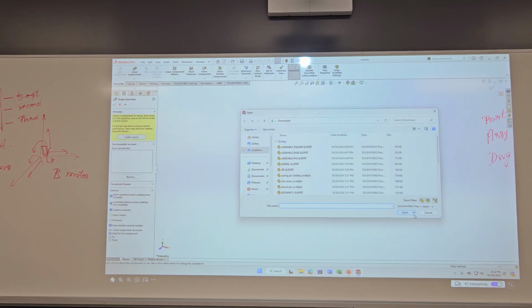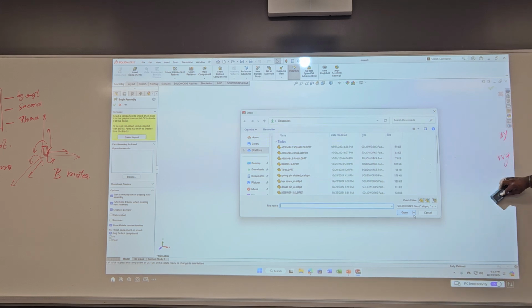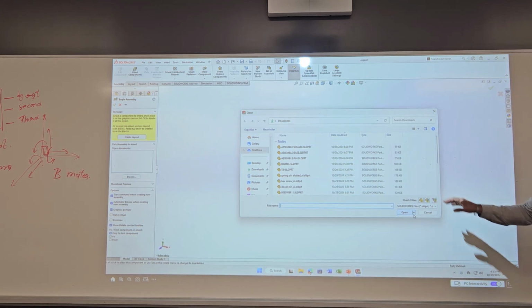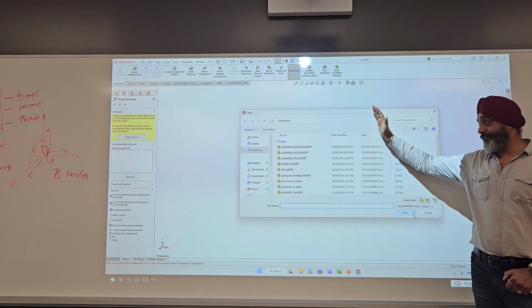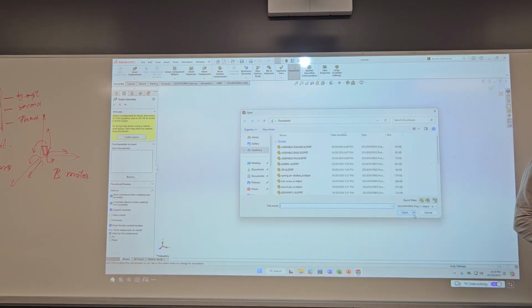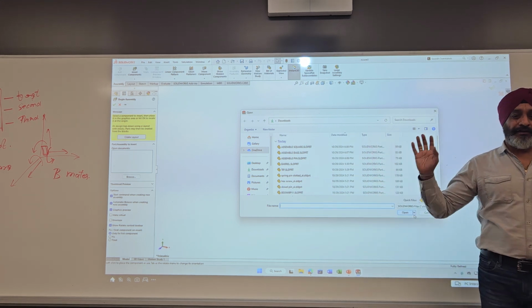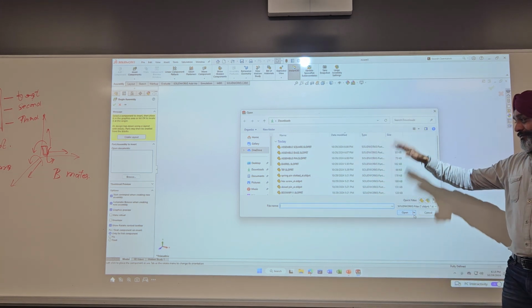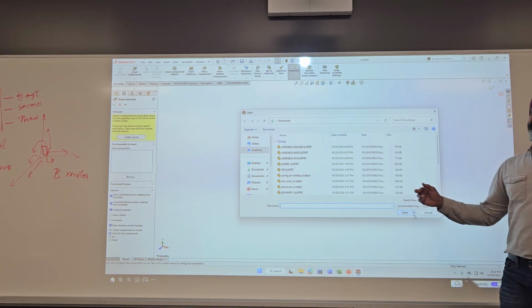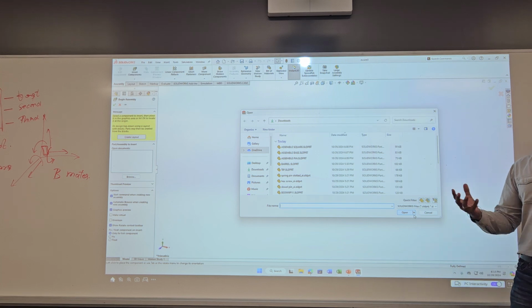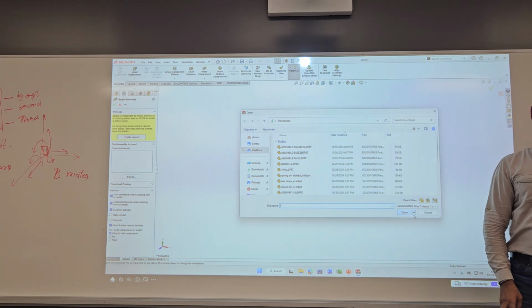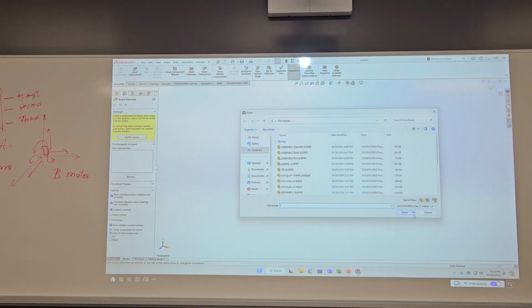And as you have noticed before, as soon as we start creating an assembly and open up a new assembly environment, it brings in the files which are available on your computer, whether they're open or not. It will always bring in a list. You need one, you click on it. If you say, no, I don't need any, I have to create more, or this is not the list which I need, you can cancel it, and you can always bring it back from your computer, your USB, anywhere, by using Insert Components. Okay, so let's exit first.